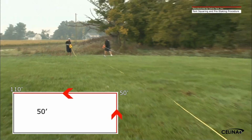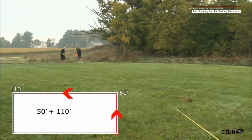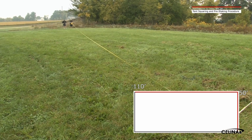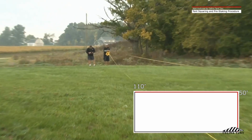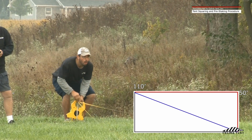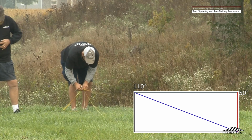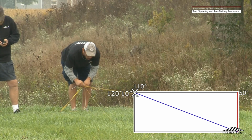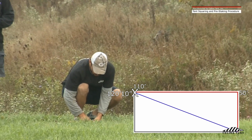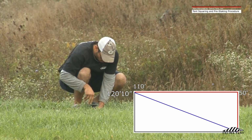With the 50-foot width of the tent added to the 110-foot length of the tent, hold the measuring tape at the 160-foot mark. Using a second measuring tape, measure the diagonal dimension of 120 feet and 10 inches away from the first corner spike location. Place the third spike in the ground where the 120-foot 10-inch mark and the 160-foot mark intersect. This spike locates the third corner of the tent.